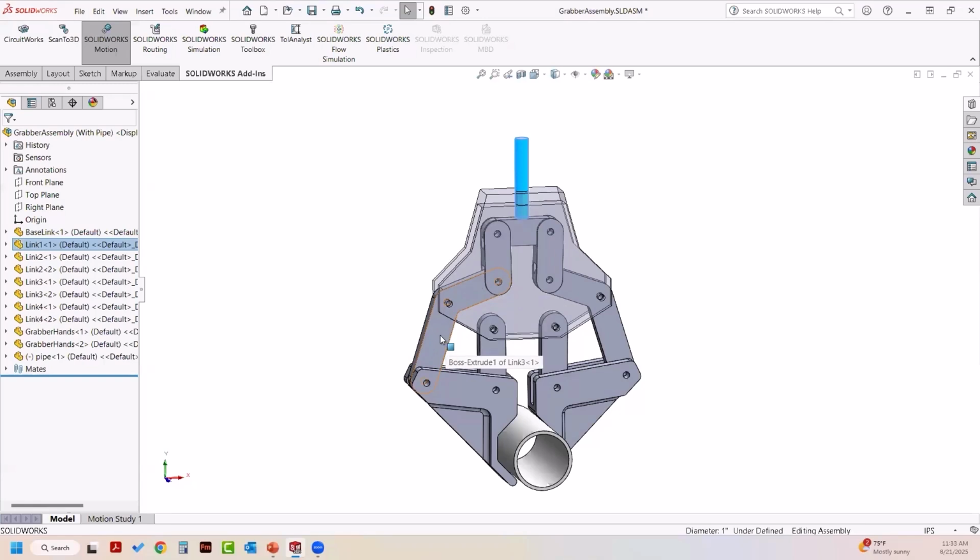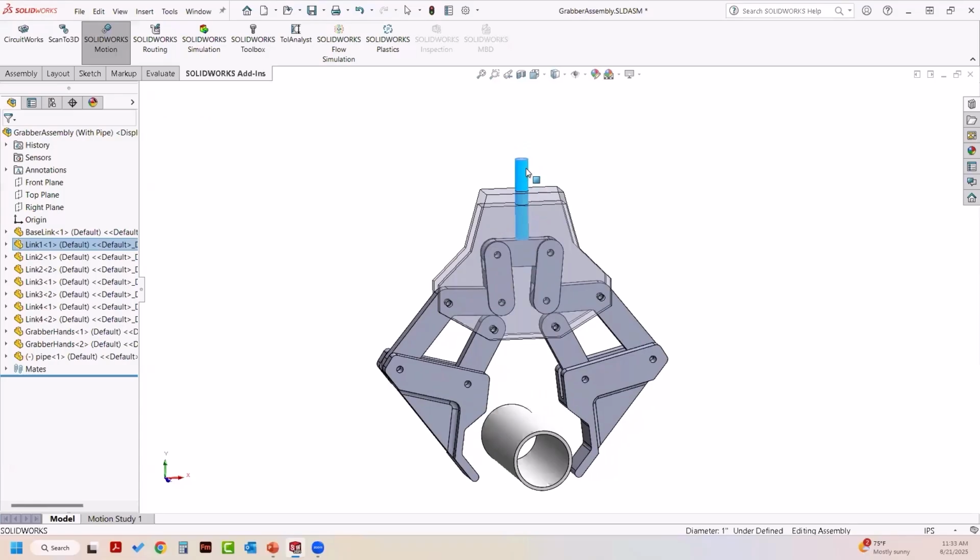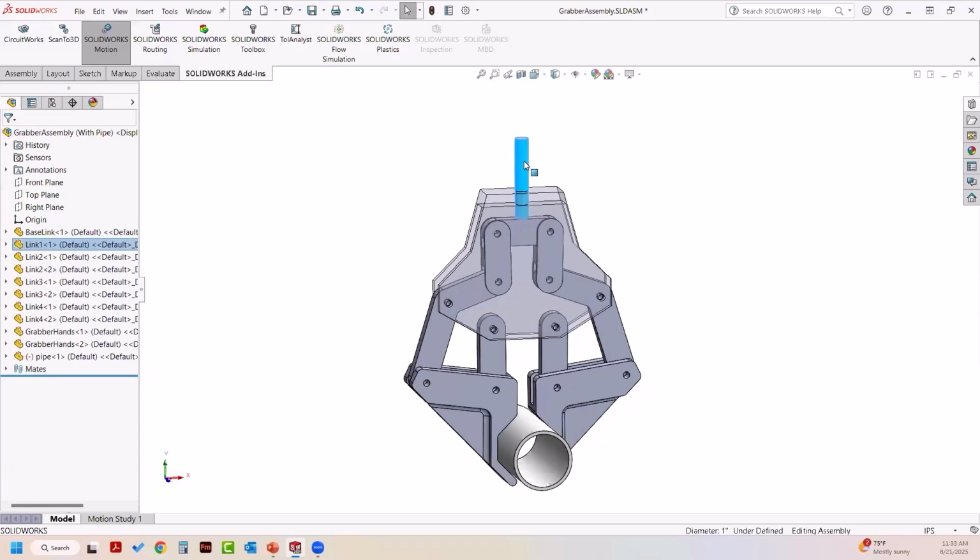We're going to analyze this component right here, this link 3 component. Let's talk a little bit more about the loads. If we apply 15,000 newtons going up on this face, and if we assume that both of these link 2 components are perfectly vertical when the load is enacted, that means that this pin right here will transmit 7,500 newtons going up.